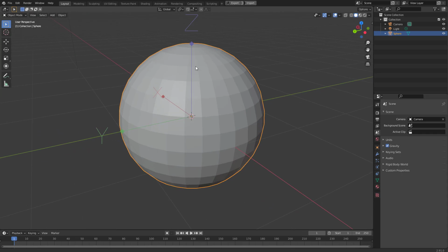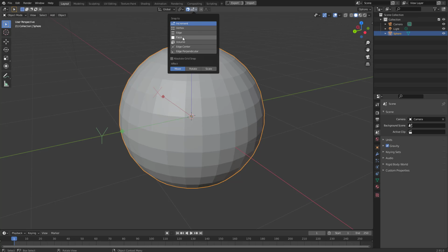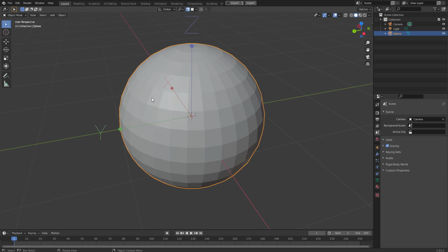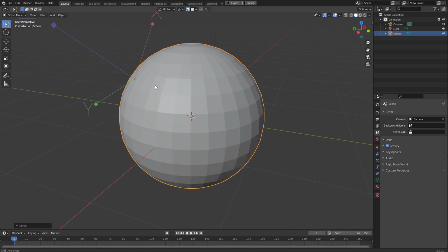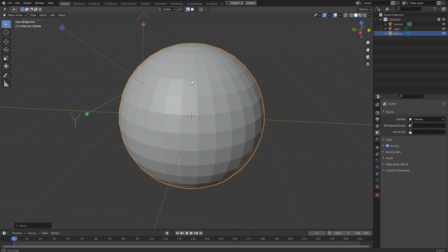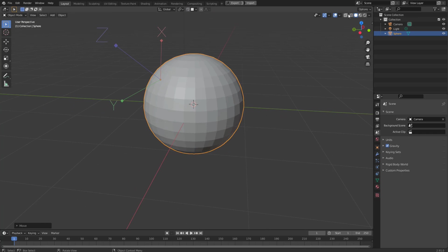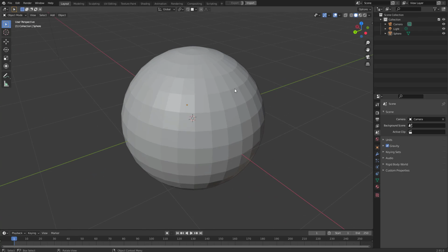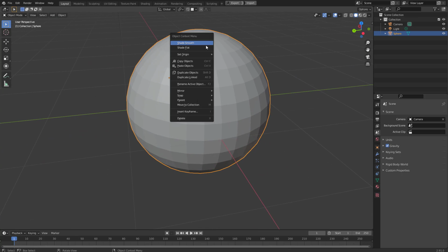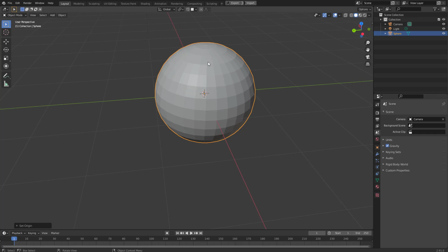Okay, so if you want to do that, you have to toggle on snapping, go to the tools like face, for example, align rotation to target, and then you can G and move. You can see that's snapping the origin to there. It's a lot of work, but I'm going to turn those things off. Anyway, I can reset the origin by right clicking and choosing set origin to geometry, I guess. Yeah, this is basically the center pivot equivalent compared to Maya.